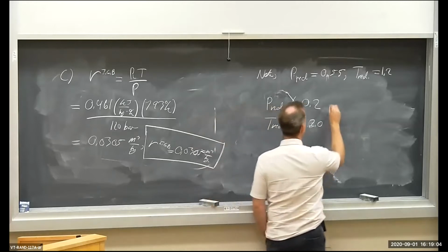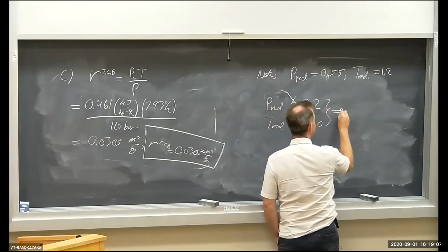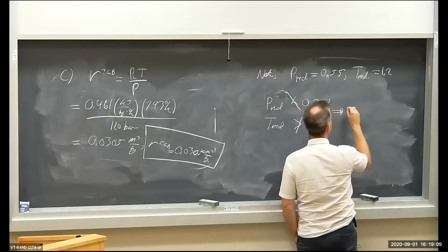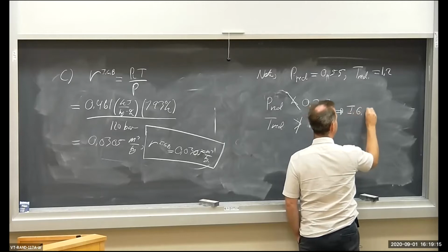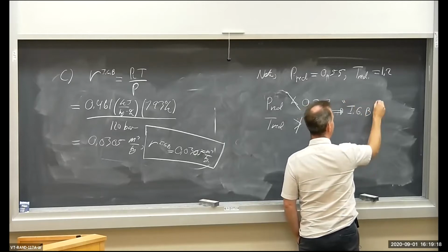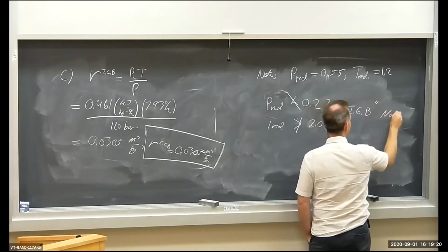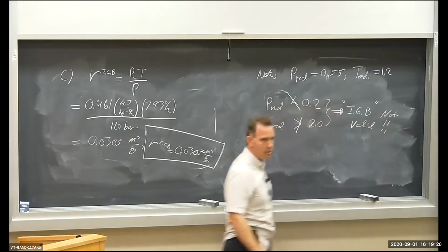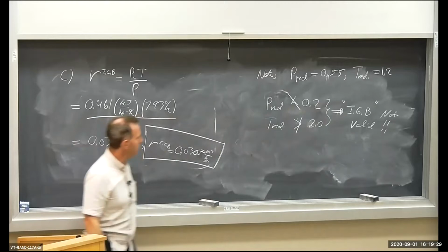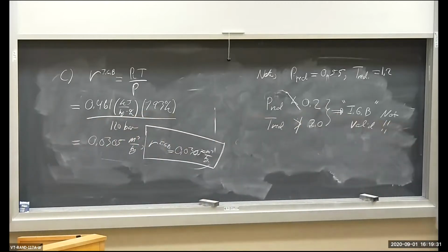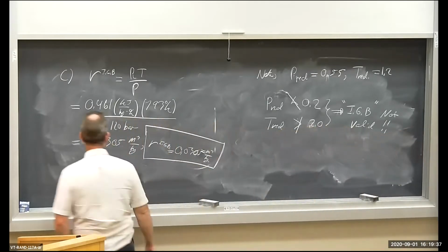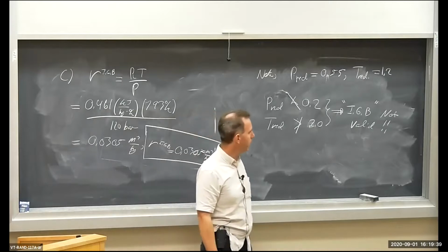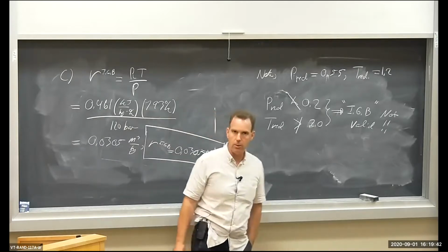So we can immediately say that the ideal gas law, Z approximately equal to 1, ideal gas behavior, IGB, is not valid. Okay? We're going to get too much error if we use the ideal gas law to calculate specific volume for this problem. And we saw that. Our error was about 10%. Usually engineers like error to be around 2 or 3%, let's say, okay?